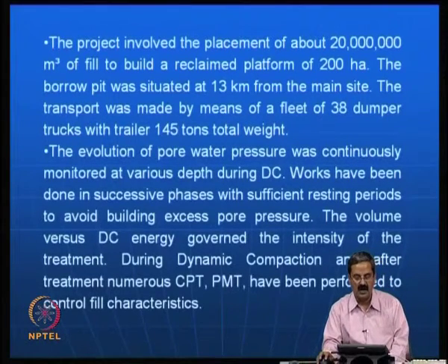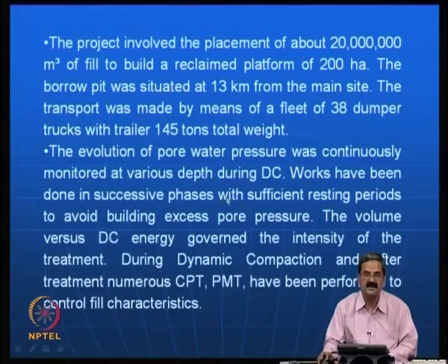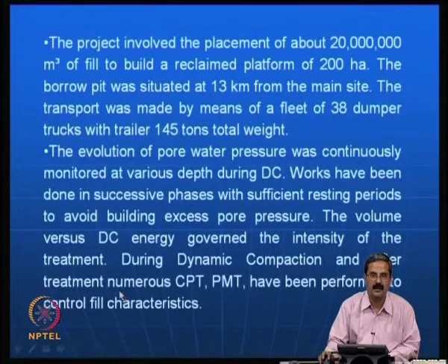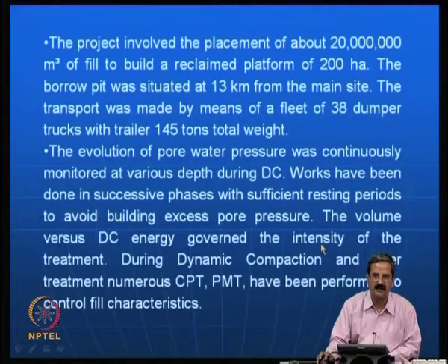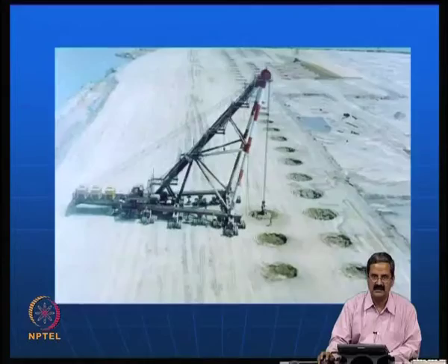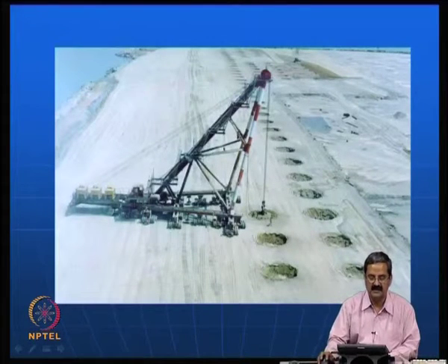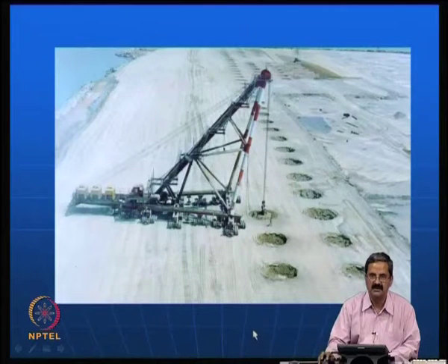So, for example, how much volume has been compacted, and the energy input into the system, is something very important, and they were able to understand this process. And after the dynamic compaction treatment, they did a number of CPT tests and pressure meter tests to control the fill characteristics. You can see that this is the process of compacting, and they have a specific sequence here.